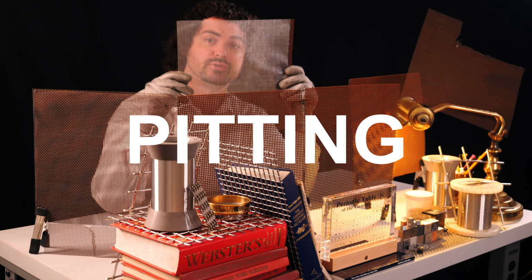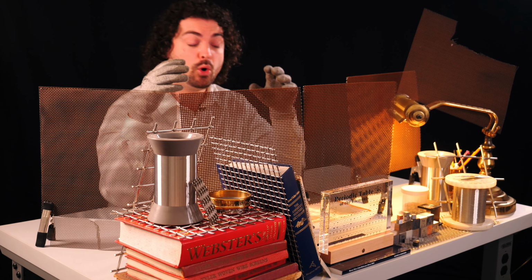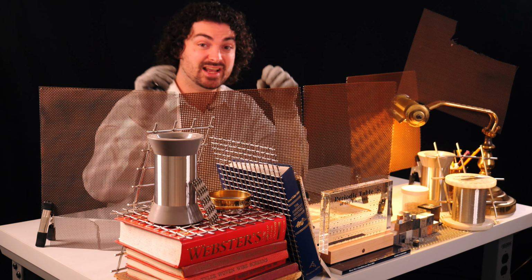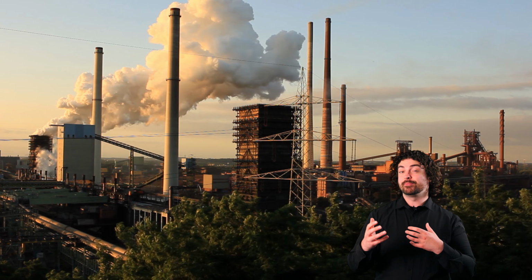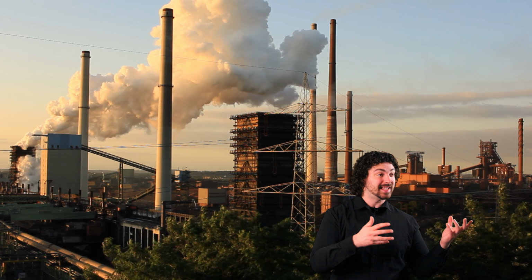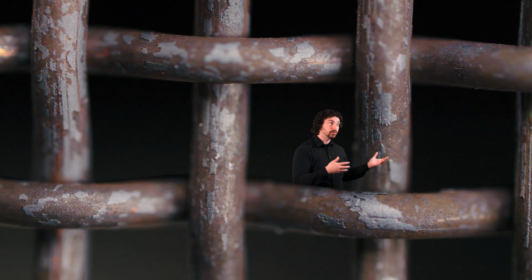Then there's pitting corrosion, which is kind of like just normal rust, except it's localized on very specific spots of the mesh. If the pitting continues, it can create craters or holes that go deep into that localized area. Not very good. So the main industries that definitely don't want corrosion are chemical processing plants. Shocker, I know. They could be processing gas and oil, plastics, agricultural sprays, anything where the base elements of their products are highly acidic or corrosive.